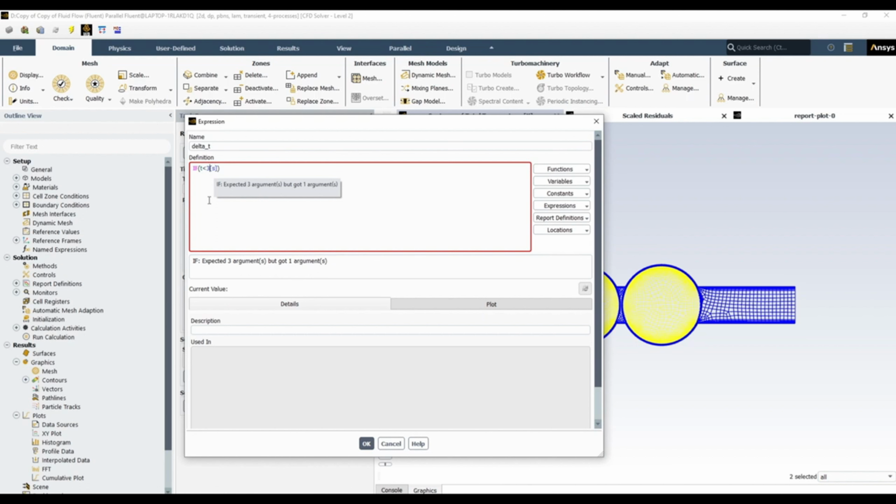You can also write, for example, 1 minute, so you can use whatever unit you like, but we want to keep it in seconds. So when time is less than 3 seconds, then comma, 0.1 second, comma. So when time is less than 3 seconds, the time step should be 0.1 second.